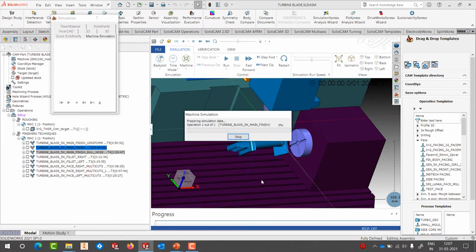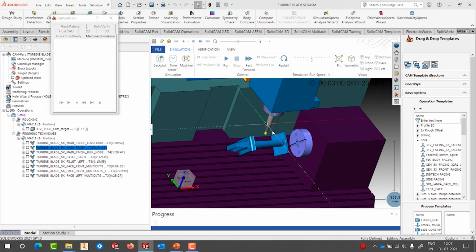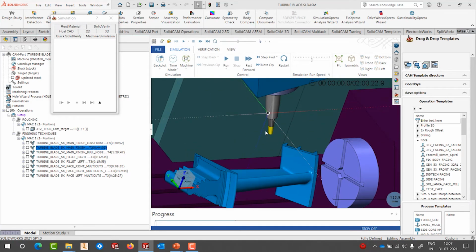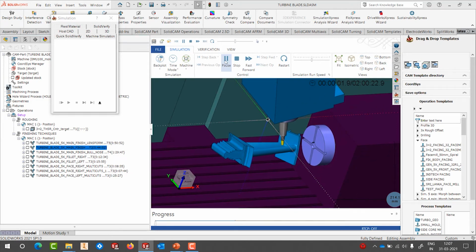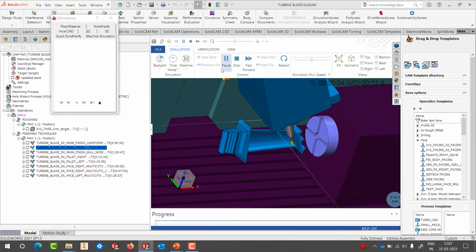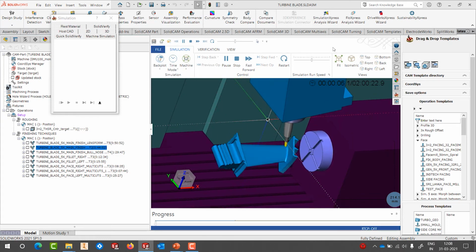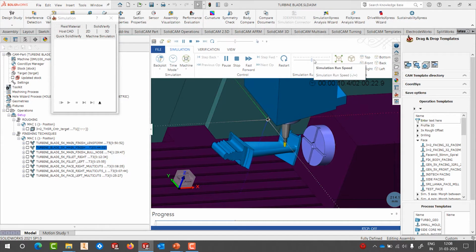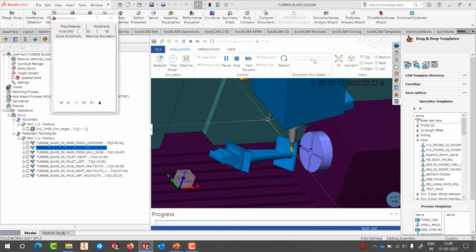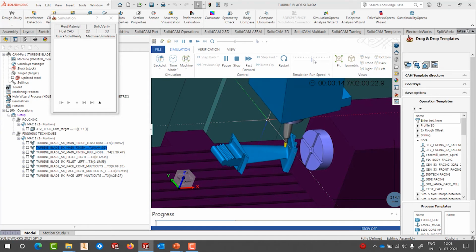Then I have got another strategy out here which uses not just the bullnose, but it uses a taper ball nose in this case. So here the taper ball nose is pretty simple. It's basically using the tip of the tool to generate the machining. This is the most common method generally people use to cut parts like this using the ball nose.